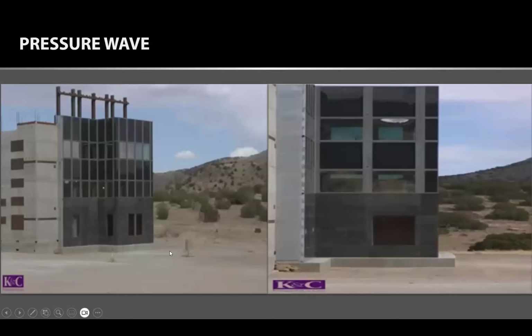All right. Now, these two videos I'm going to show you here are very slow motion videos of explosions occurring that are testing curtain wall and storefront systems on the exterior skins of these buildings. The first that you're going to see, and right here, if you can see my little mouse circling around that device, that's about 10 pounds of TNT. You are going to see the hemispherical shockwave explode on both of these images, and these curtain walls in these systems and all the glass must maintain their structural integrity and not enter the occupied space. Otherwise, it runs the risk of complete catastrophic failure.